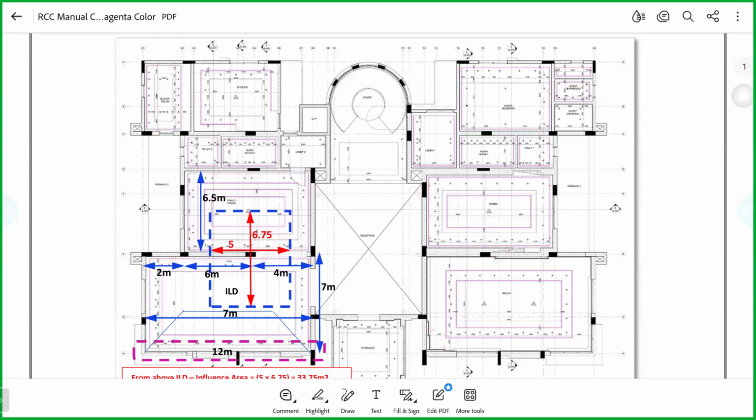In any case, for both calculations we need to do the shear check. But in a frame structure, the beam connected to the columns takes the shear. In a flat slab, which connects directly to the slab, you don't have sufficient stiffness, because the slab thickness in general can be 20 centimeters and not more than 23, and it's very rare in buildings to go more than 25 centimeters of slab thickness. So most probably the slab thickness is within the range of 20 to 25 centimeters. You get my point? Okay.